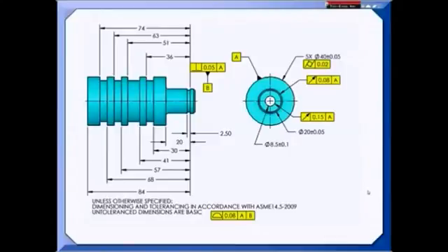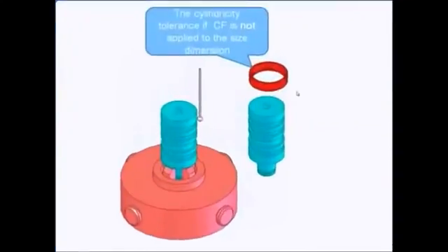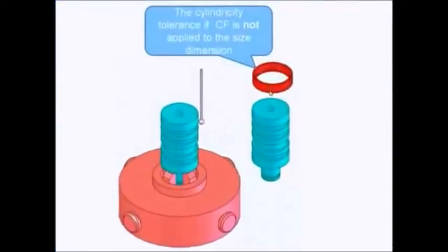Well, we have a little bit of a problem here because cylindricity is an individual tolerance, and I really don't have one feature here. I have 5 features. There's 5 diameters because of the interruptions. So the cylindricity applies to those 5 diameters individually. This is showing you how long my cylindricity tolerance zone would be. So it's not keeping all 5 acting like one nice cylinder. It's keeping the individual cylinders acting like a nice cylinder, but no relationship between them.